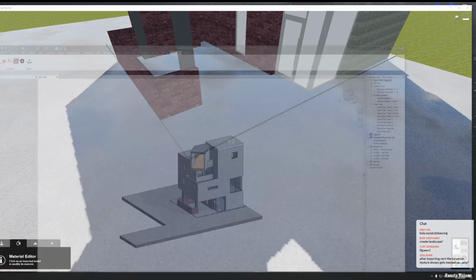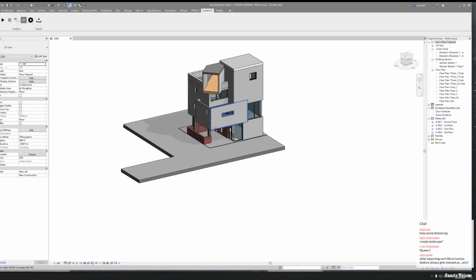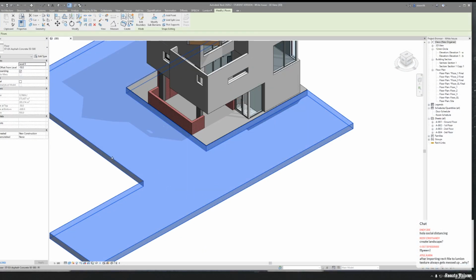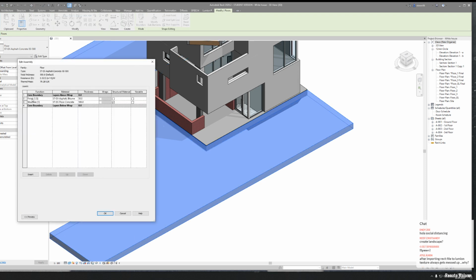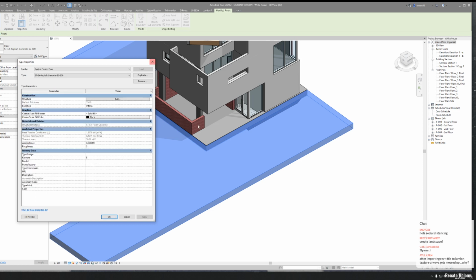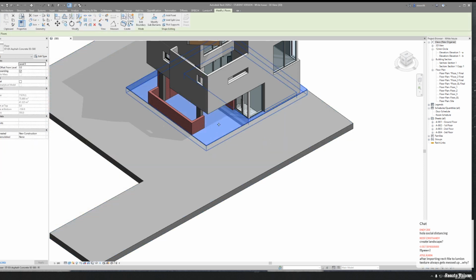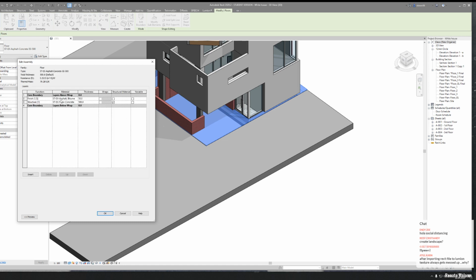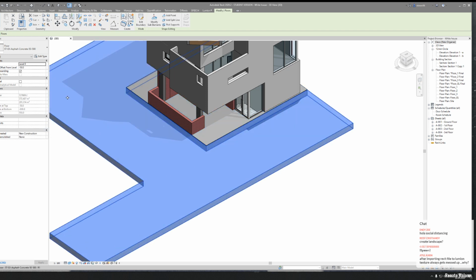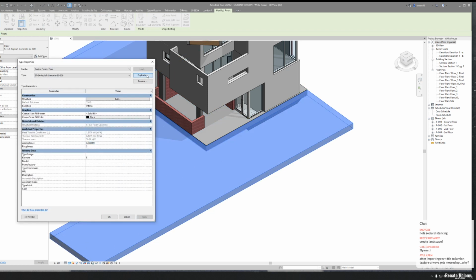We should go back to the Revit. We should select this object, go to the additional type, edit this material, and as you can see, the finishing here is the asphalt, right? Okay, awesome. Let's check this material. Let's go inside, edit. And here's also asphalt. Not cool. Let's change it. First I want to duplicate it. Duplicate, and I will call it just asphalt, without anything.